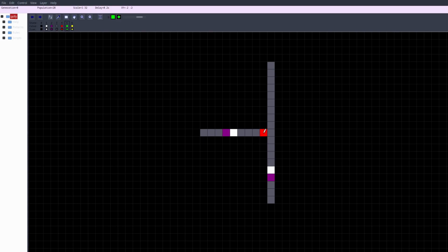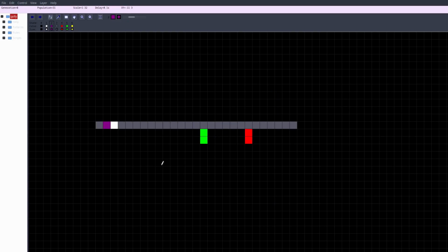Changing the red cell to a green one produces an AND NOT gate. Only if the lower signal is present, but the left signal is not present, will we get an output at the top. There we get no output. Here we do get an output. If red or green cells appear in a pair, they will not change state when a signal passes by. This can be used to create permanent diodes.